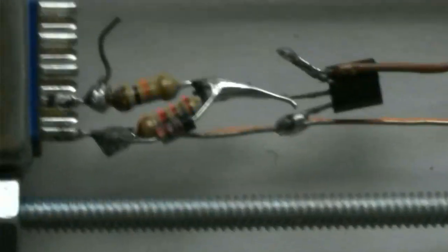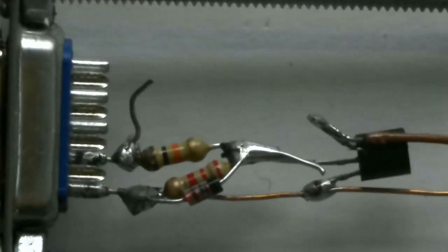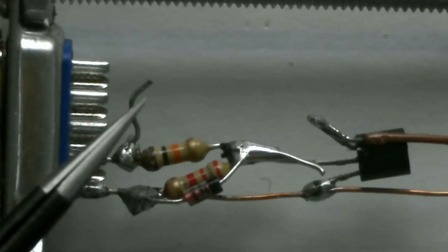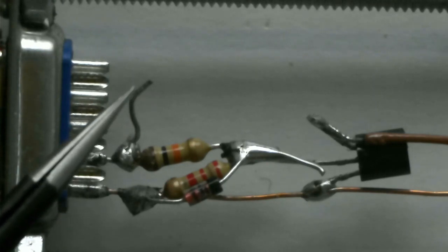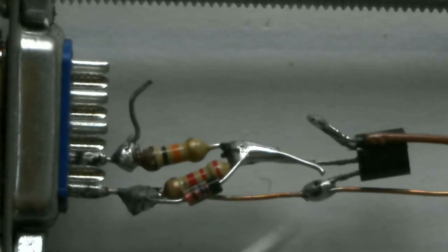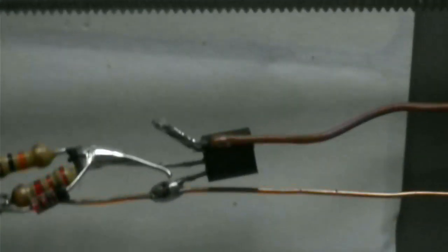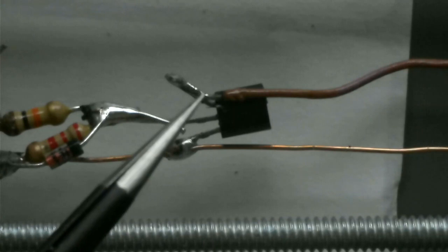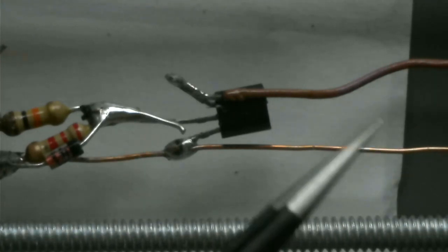Here's my little circuit here with the transistor, like I said. Let me get a little pointer here. This little wire here is my test point. That's what I had my alligator clip hooked to. That's what showed you the 7 or 8 volts on the meter display. That's what that's for. Since I don't have the actual repeater to plug this into, I just took a test lead and clipped it onto the collector of the transistor. And this is my ground.